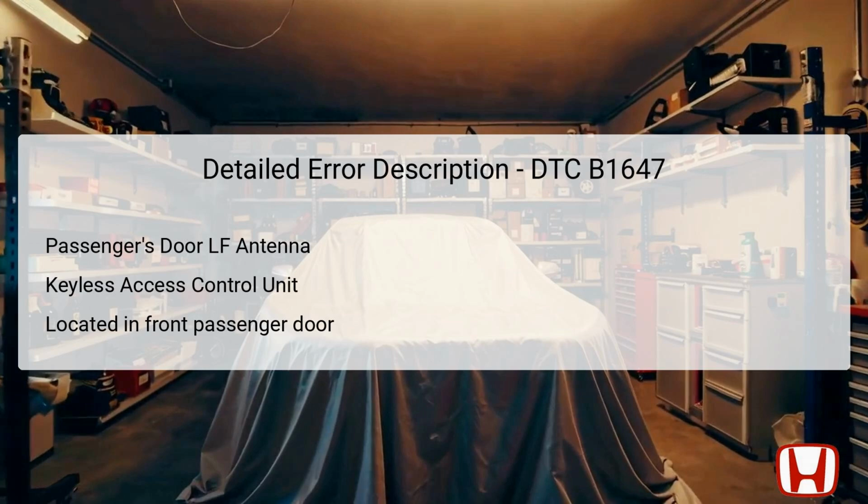In terms of location, the components involved in this error are situated in the front passenger door, particularly around the outer handle, which houses the necessary antennas and wiring for the keyless entry features. Any malfunction or short circuit in this area can significantly impact the vehicle's ability to respond to keyless entry attempts. Hence, identifying the exact source of the malfunction is crucial in restoring normal function.